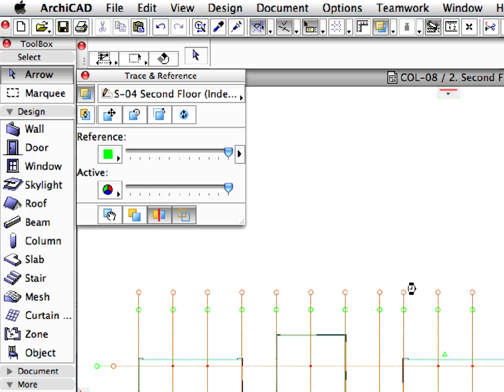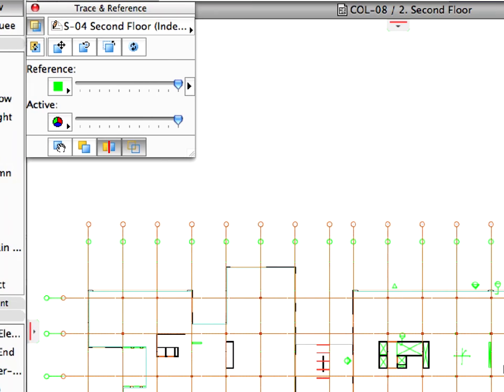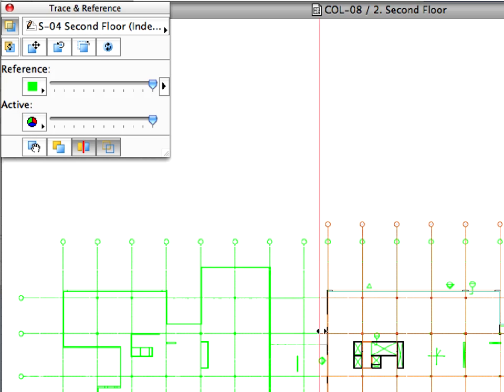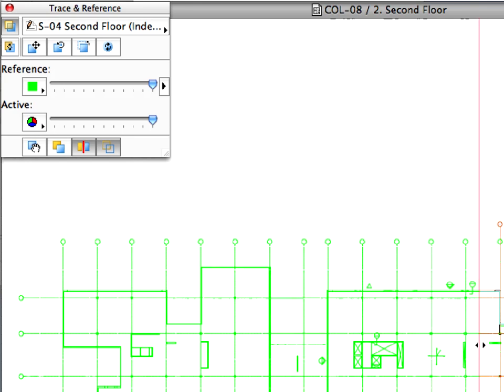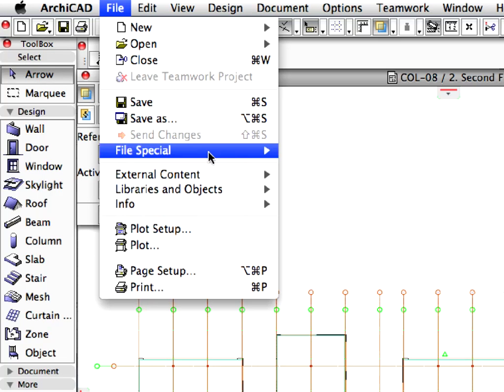The XRefs on the worksheets have been replaced with the second version of the drawings. The same result can be achieved if the original XRefs are overwritten with the new ones. In this case, ArchiCAD updates the referenced files automatically. Go back to the XRef Manager again.